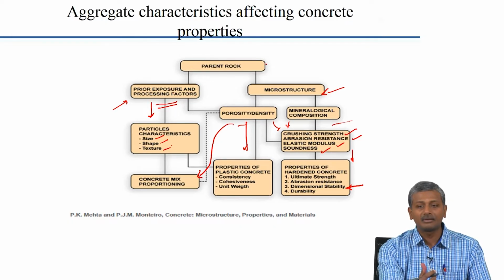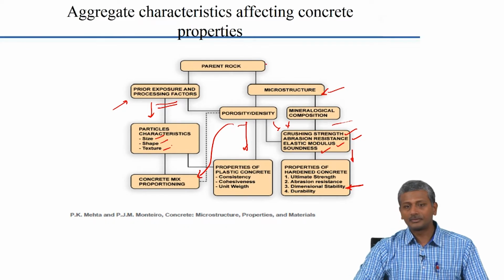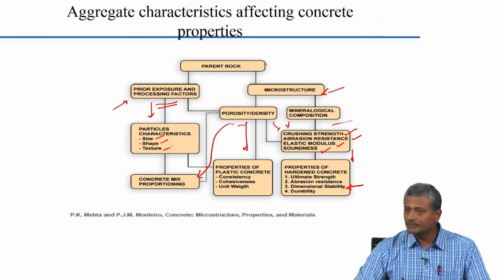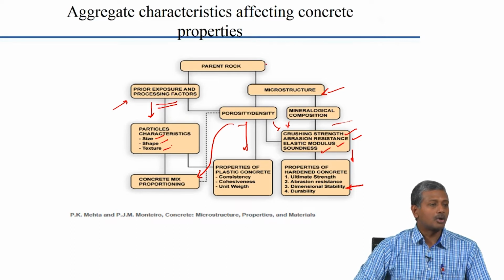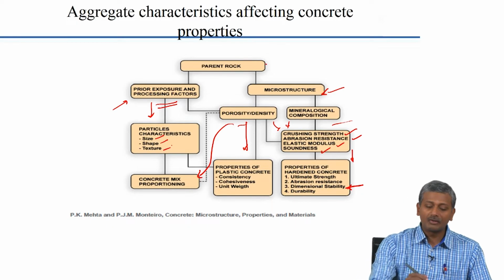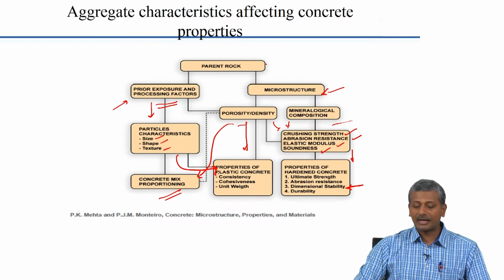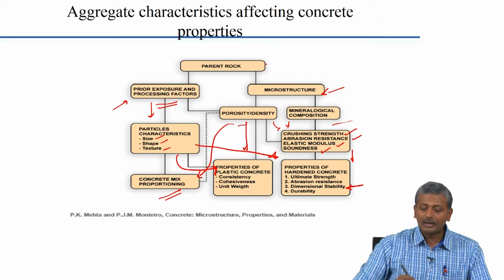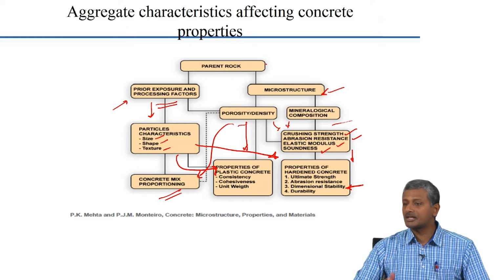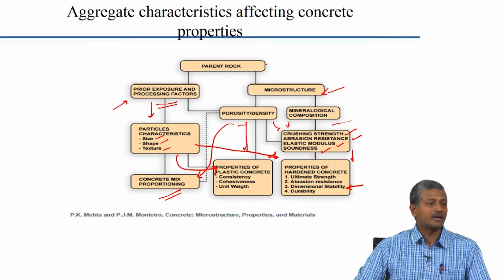You know very well that river gravel, because of the continuous weathering action of the water, is nicely rounded and smooth. On the other hand, aggregates that you obtain from quarries are rough and angular, right. So, because of that you get very different bonding characteristics with the cement paste, and that will obviously affect the way in which you mix proportion your concrete, and it will also affect the concrete properties and probably also the hardened characteristics, because the bond between paste and aggregate will differ based upon the surface texture of the aggregate, for instance. Okay. Smoother aggregate will give lesser bond as opposed to rougher aggregate.